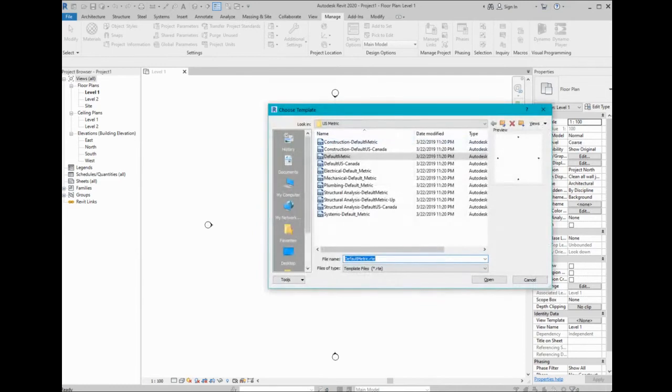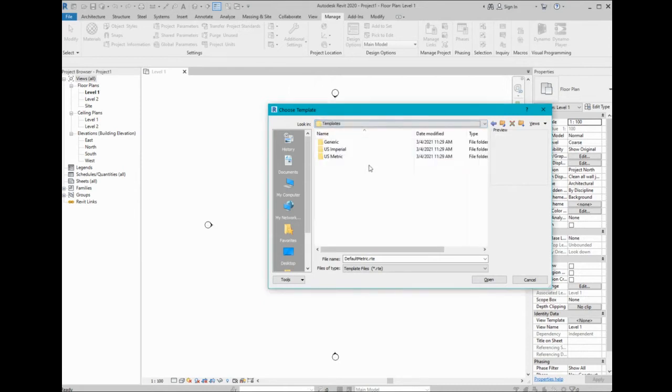So when you click on Browse and you go here, it's supposed to open automatically. But if it didn't open automatically, just make sure that you follow this path. So you'll go to C, Program Data, Autodesk, Revit 2020, for example, or 2019, depending on what you have, and then Templates. In Templates, you will find Metric and Imperial. This is not only to open a template. This is also to load families, to load any doors, windows, furniture, all of these families. You will have to come here.